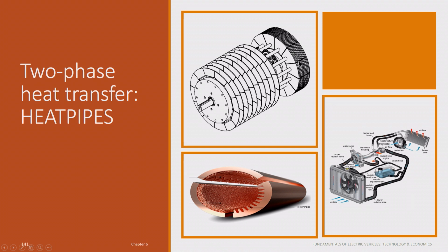These are the heat pipes, and then there are many closely spaced fins at the other end of the heat pipe, and inside here, what is not clearly visible, is a radial fan, axial inlet, radial outlet, which will blow a strong gust of air and take everything away. So, whatever you are seeing here which is being done by the liquid and the hoses is being done by the heat pipe, and then finally what is colloquially called a radiator, which is a long network of pipes with fins through which a fan is blowing, that fan is kept over here. So, you do not have any leakages, there are no moving parts.